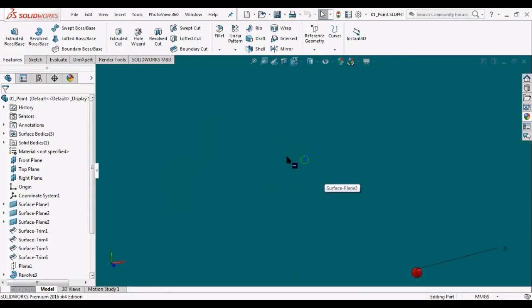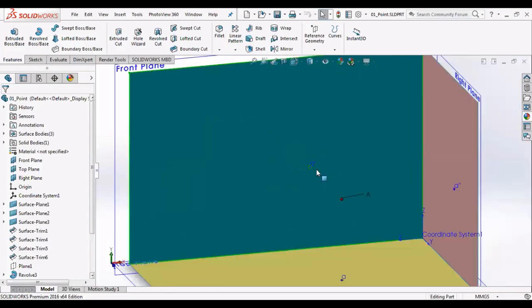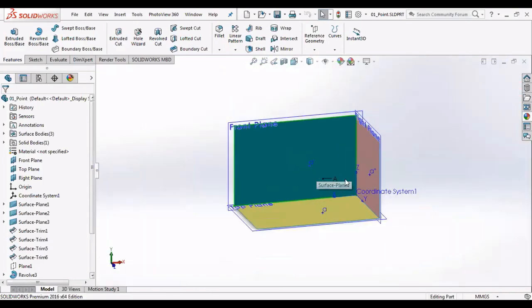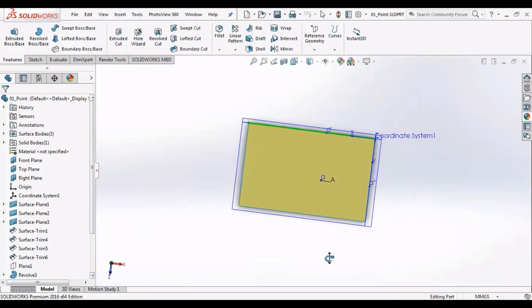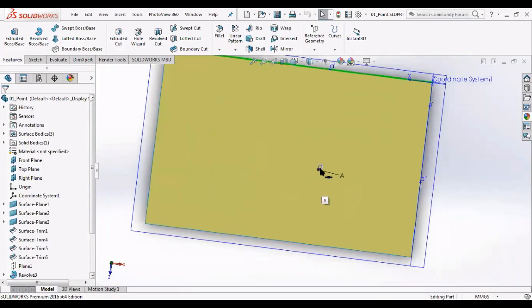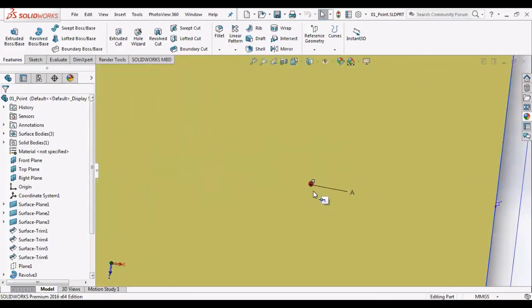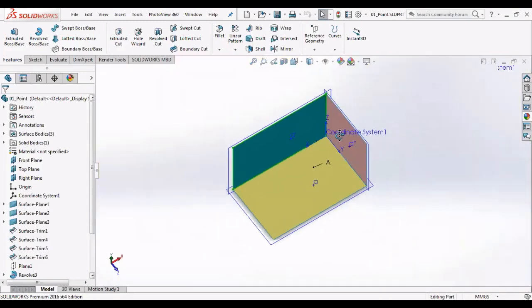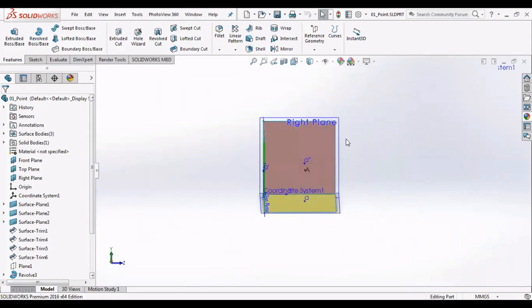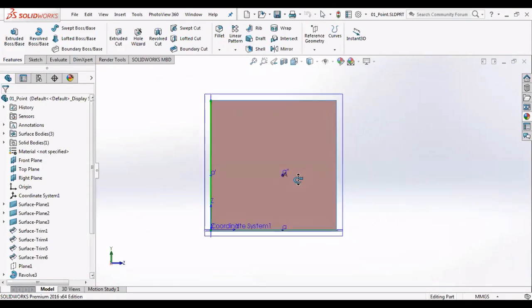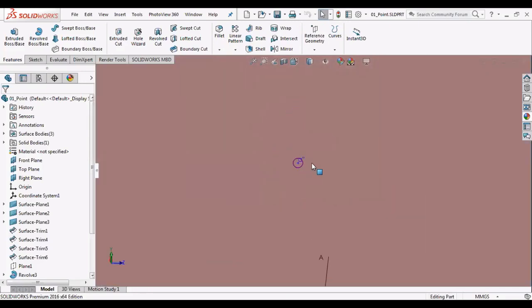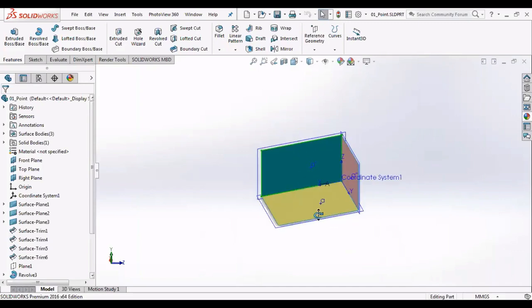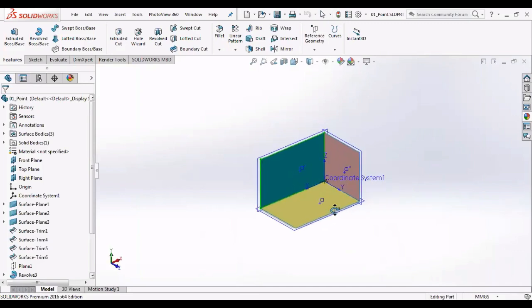Point a dash, the green one. If we project to the yellow top plane as an orthographic projection, we will generate point a, small a without any dash. And to the purple plane, the profile plane or right plane, we will generate a2 dash. So it is this kind of projection.